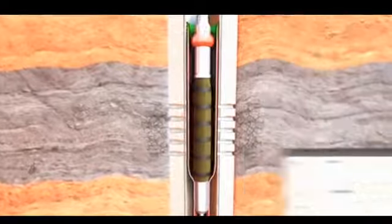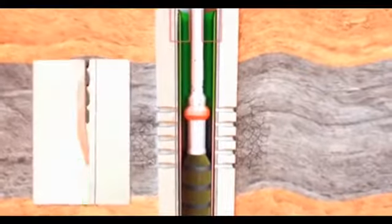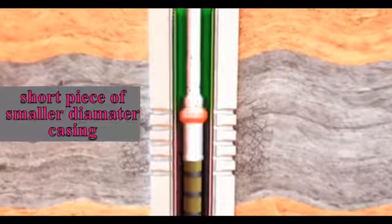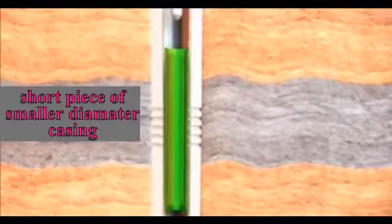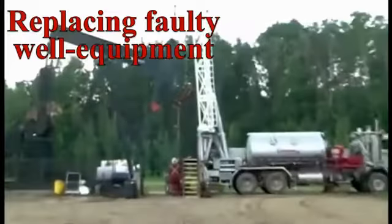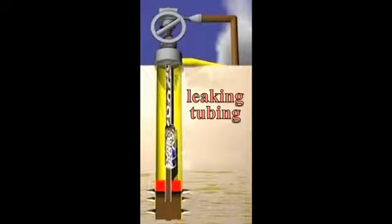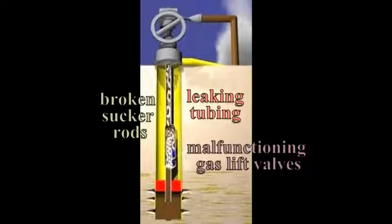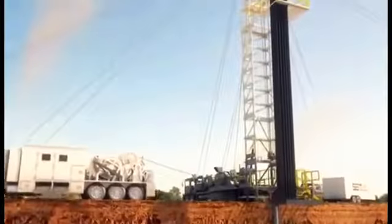Repairing casing leaks can also be fixed by setting a scab liner over the leak. A scab liner is a short piece of smaller diameter casing with packers on both ends or a packer that expands outward to seal the leak. Repairing faulty well equipment. Here, worn-out downhole equipment is replaced, such as leaking tubing, broken sucker rods, malfunctioning gas lift valves, or leaking packers. As you can see, maintenance operations are vital in maximizing oil field production. They require good engineering over the life of the well and the field.